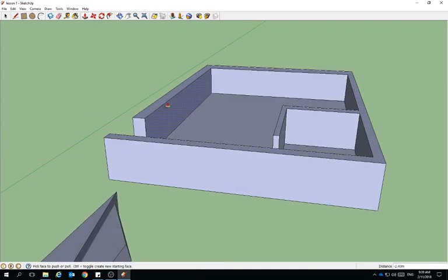And I can check that by using my measuring tool. So I can go to any of the corners, go to the endpoint, drag all the way down to the other endpoint, and it says 2.4. So I know that that is exactly 2.4 meters high. Okay, so that's a measurement we'll use typically for our final assessment task for this unit. All right, so I've gone through, I've done that.